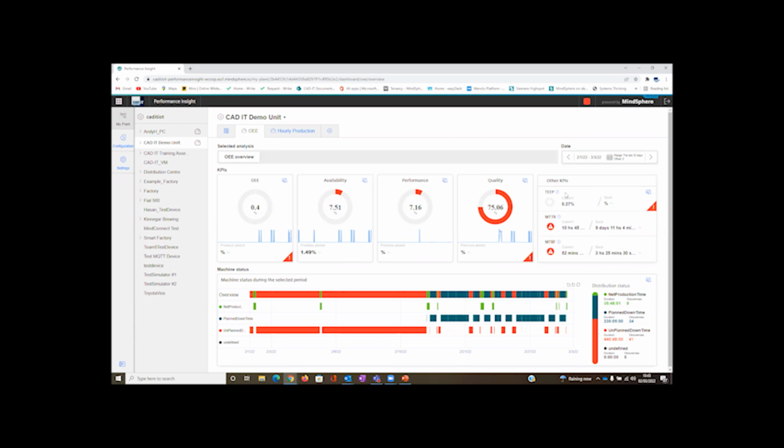It's purely how much capacity is available. So that gives you a much lower OEE score if you are only running 2 shifts and you have a number of maintenance schedules. So you only actually run the machine a certain percentage of time. You could use that metric to determine that if you made some changes within your business, you've got more capacity, so you could increase productivity. So that might be helpful, using this metric to determine, well, maybe we don't need to buy new machines, we just need to get more out of the ones we've got by utilizing them more. And also, of course, which machines could you actually get more out of by comparing them.